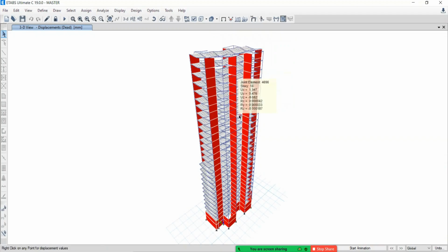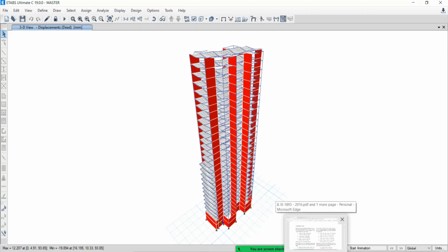As I told you, modal analysis is finding out the dynamic properties of your structure under the seismic and wind loading. I want to see, but all those 78 mode shapes or deformed shapes of the structure are not useful. The code recommends that we concentrate on the first three modes. You have to check three modes, and ensure that in the first mode and in the second mode there should not be the presence of torsion.